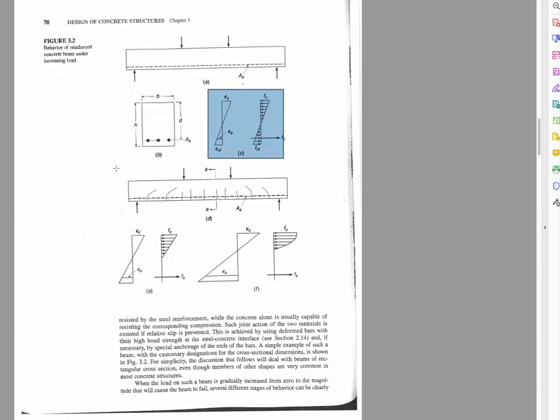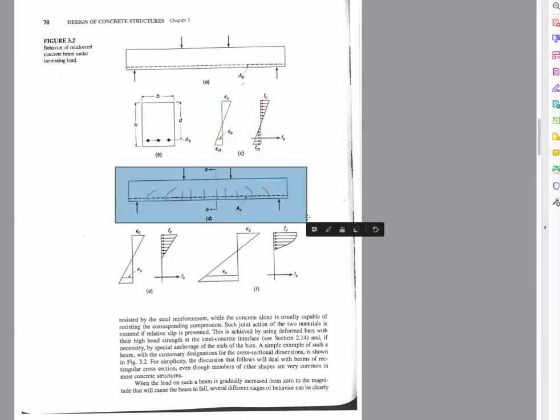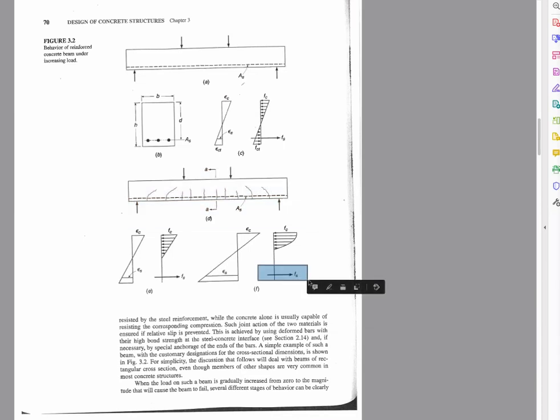And this is showing quite an extreme example where it's actually cracking and showing that lousy performance of concrete in tension, but the steel is there to hold it together, so it's not horrible yet. And if we look at the response to this, we find that the steel is in tension, holding that just fine.